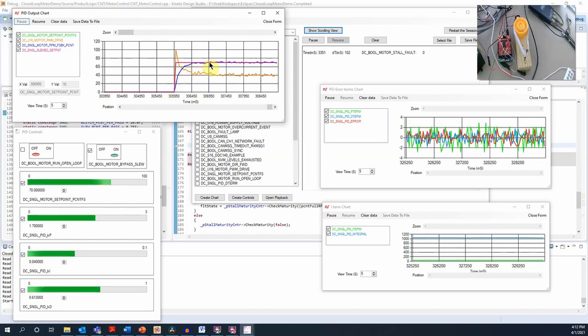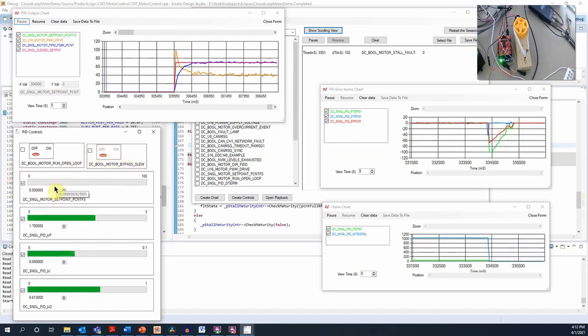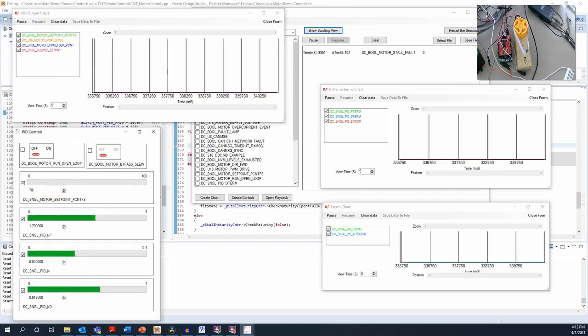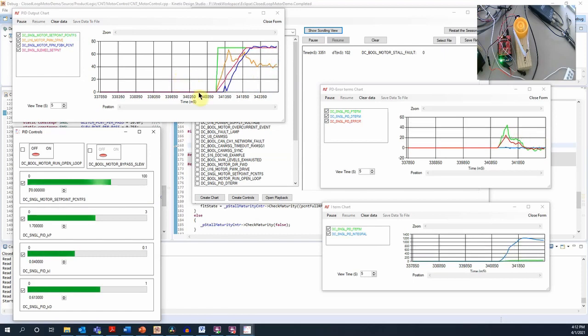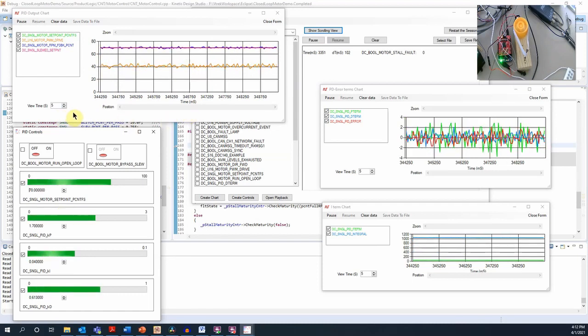during this ramp up. And if you do the same thing then with the slew rate on, we'll see that doesn't happen because we're coming up at a slower rate. So that's one of the things you want with a control system: when you're spooling up or spooling down, you need to have still enough control to be able to stay closed loop. Otherwise, you'd have a system that's essentially running open loop for a short period of time.